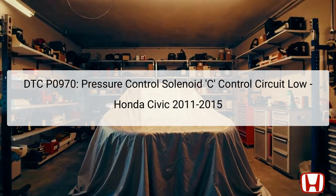The Diagnostic Trouble Code, DTC P0970, refers to an issue involving the pressure control solenoid C in Honda Civic models from 2011 to 2015. This code indicates that there is a fault in the control circuit for the solenoid, which is responsible for regulating pressure within the continuously variable transmission, CVT. The solenoid is vital for proper transmission operation, affecting performance and fuel efficiency.